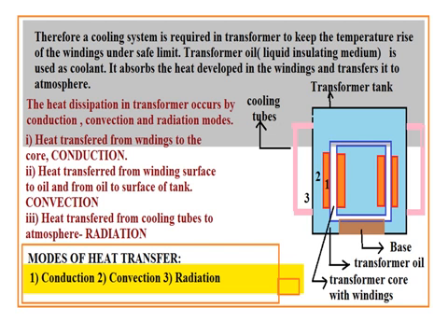and radiation process. Conduction means the amount of heat developed inside the winding is transferred to core or some solid material. Hence, the heat is transferred by conduction process as shown in figure number 1. Then heat developed in the surface of windings is transferred to transformer oil. That is, heat is transferred from windings surface to transformer oil. That is convection, number 2.